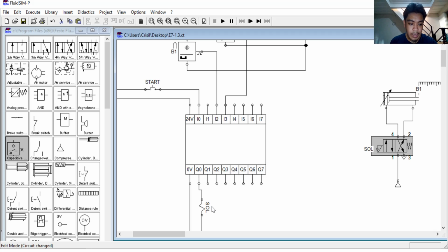By means of a label, the valve solenoid can be linked to a valve that is solenoid operated. So here it is electronically or wirelessly connected to the switch here and here. As we turn on the start push button, it goes within the logic module, and our Q0 connects to our SOL here at the 4-way valve, which then activates the piston or the double acting cylinder.